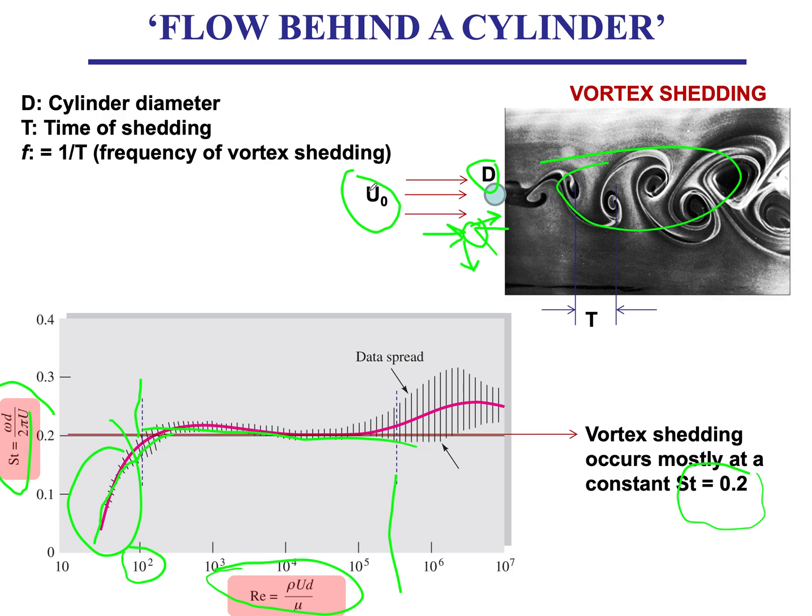That gives you, by playing with the velocity, a different frequency. So this is a basis for pretty much wind musical instruments. So now when you think about wind instrument music, you want to think about the Strouhal number in there, because there is the velocity scale and the length scale, and from those two we get a frequency, which is the frequency that we hear, the oscillatory frequency.